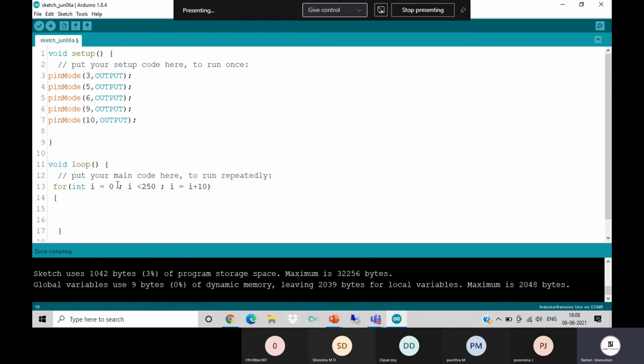Earlier, when we wanted to turn something on or off with the LEDs, we used the digitalWrite command. Fine. For the PWM functionality, we will require the analogWrite function. It also takes two parameters. In this case, parameter 3 is our pin number, and parameter i is the value which we want to send, from 0 to 255, for the right amount of intensity.